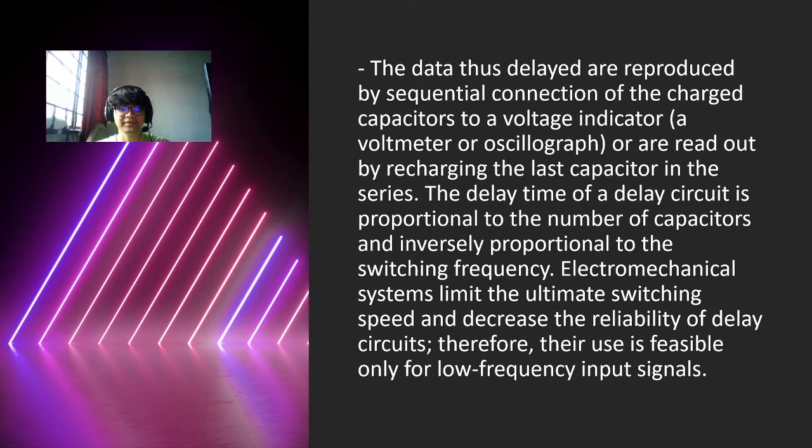The delay time of a delay circuit is proportional to the number of capacitors and inversely proportional to the switching frequency. Electromechanical systems limit the ultimate switching speed and decrease the reliability of delay circuits. Therefore, their use is feasible only for low frequency input signals.